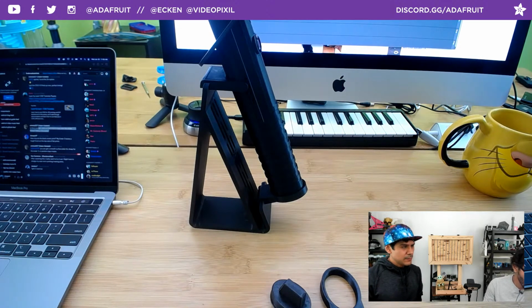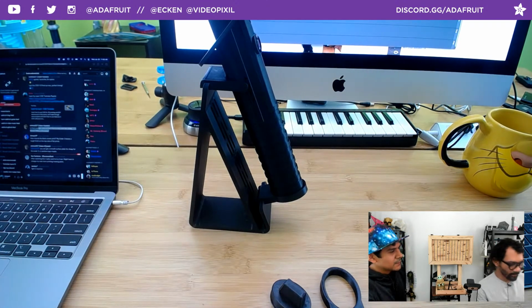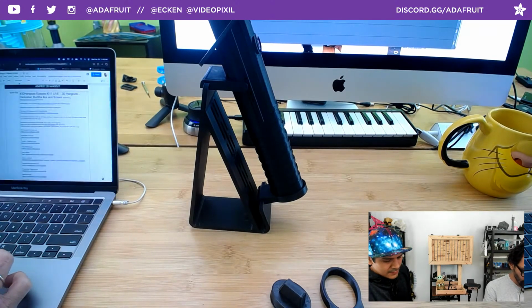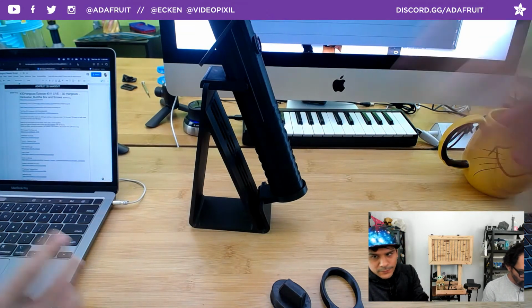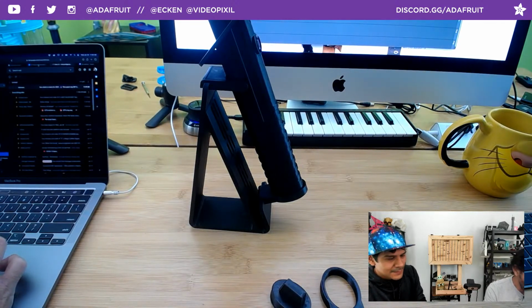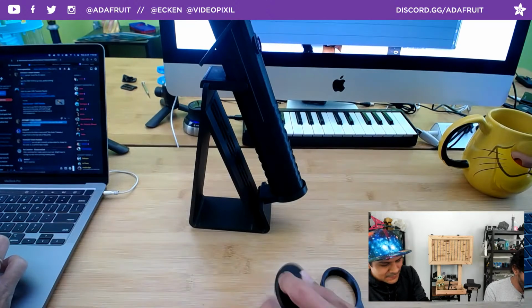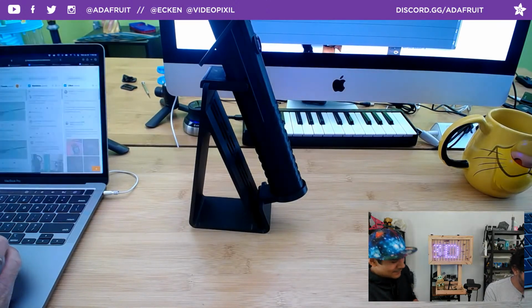And I think at some point we're going to make a video about how you install the bundle, and what's the method and why. There just isn't enough space, and you want to put only the libraries that you need. For this one, it's the NeoPixel library, the LED animation library, the Bluetooth library, and the LIS3DH, which is the model number for the accelerometer. So those are the libraries.